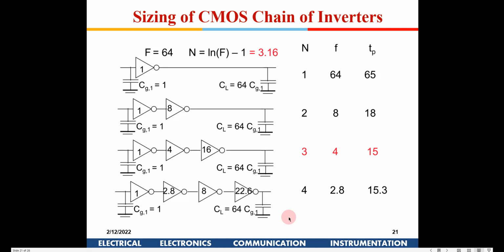No, no. W by L is a parameter which is available for a VLSI designer. In any circuit, W is a thing which can be easily changed. There is no problem at all in having variable W and L also for that matter. But in most digital circuits, we do keep L constant, because the layout becomes simplified, but W is not at all an issue.